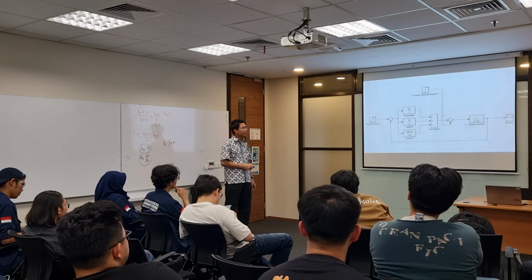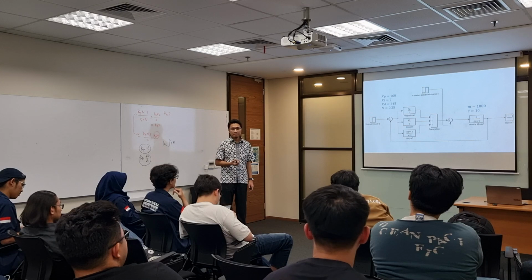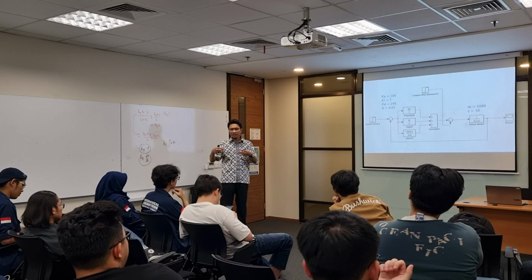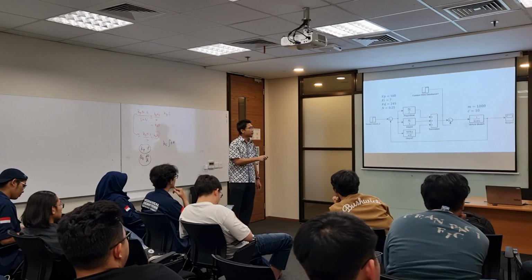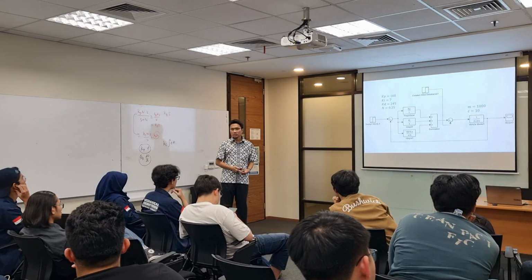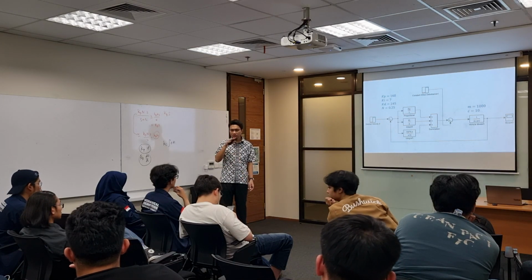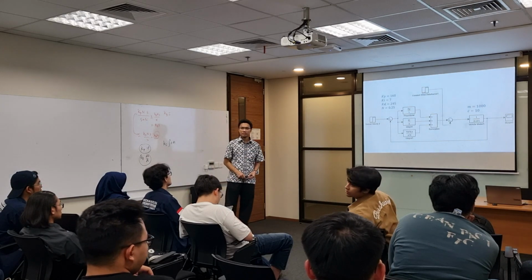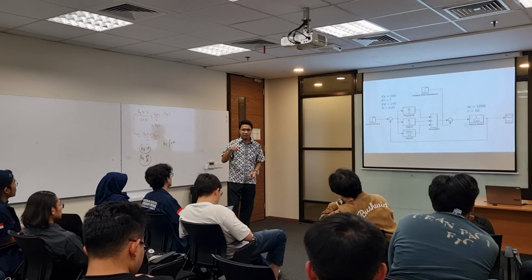If you try to simulate this, you can see that when the derivative constant is very large, it reaches the steady state much later compared to this setting. The overshoot is smaller, but you reach the steady state longer. So be very careful when you are using the D part.